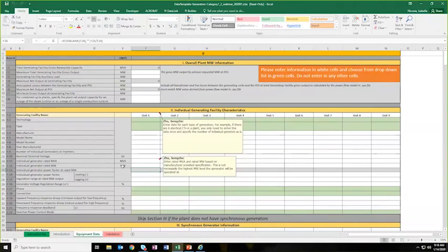It's really just meant for information based on your MVA and the rating in megawatt. What is the power factor for this combination of megawatt and MVA? Here the MVA and the megawatt, you can just enter the rating number directly from your manufacturer sheet. It doesn't have to match your capability test report. The design data is a reference point for us. We are going to review all the information you provide: this information, the capability test report, and your power flow model. Make sure that your Qmax, Qmin in the power flow model can be supported by both the manufacturer data and your test report.